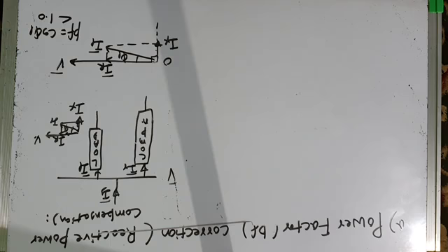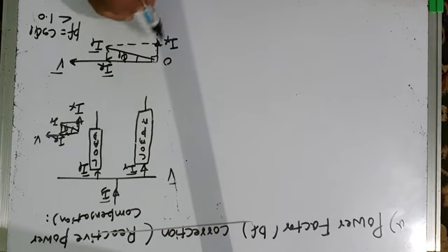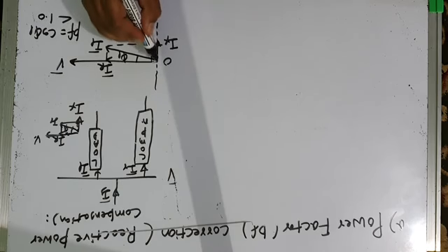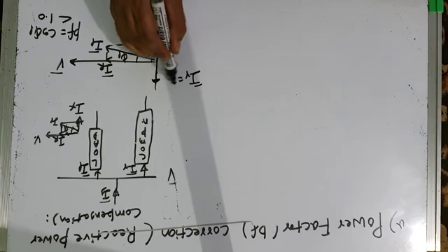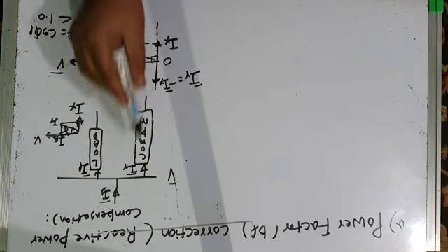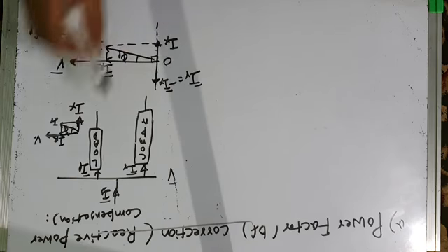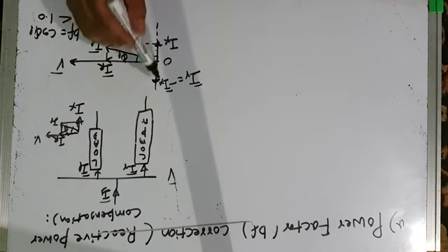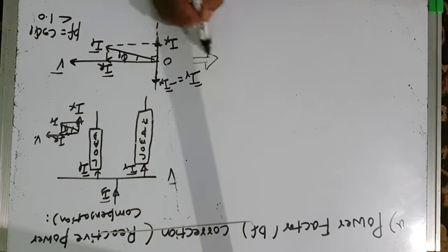In order to make power factor unity, the compensator should inject a current I gamma into the system, which is equal to minus Ix. So that will be this. This is the length of Ix. This is the length of I gamma, which is equal to minus Ix. Now we can see this is the current injected by the compensator or current drawn by the compensator. And what is this equal to? It is equal and opposite to Ix, where Ix is the reactive component of current drawn by the load. Now this phasor is equal and opposite to this phasor, so they cancel out each other, and the result is that there remains only the in phase component of current, and your phasor diagram will be modified like this.